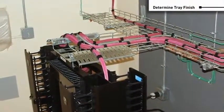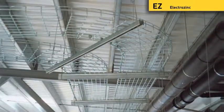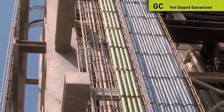What tray finish should you specify? Is it for interior or exterior use? Our standard electro-zinc trays work for most interior applications. Use hot-dipped galvanized tray for general exterior applications.